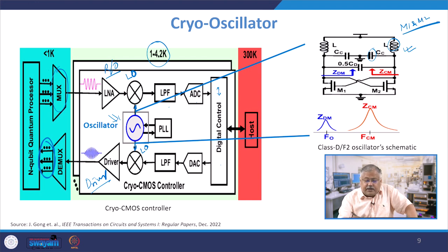This is where the positive feedback comes into the picture. I am giving an input signal to the gate, current is flowing through this NMOS, this current develops a voltage here, this voltage feeds this M1 and so on and so forth. So, this gives you a positive feedback, and this is where you store the energy for the circuit, and this is where you are drawing the VDD power rail from the top, and this is the ground here, right.